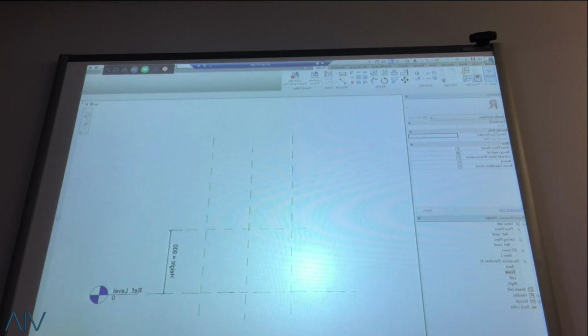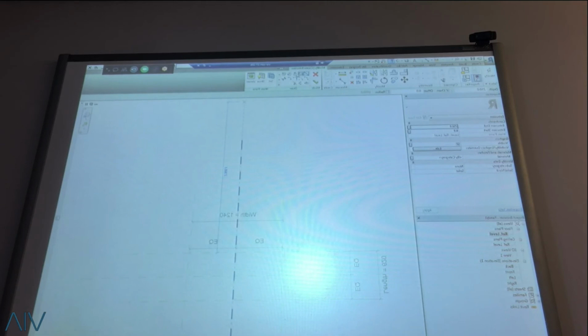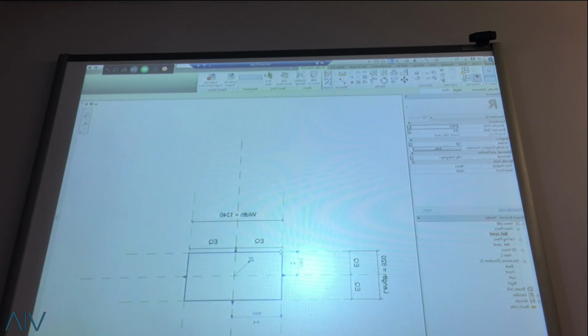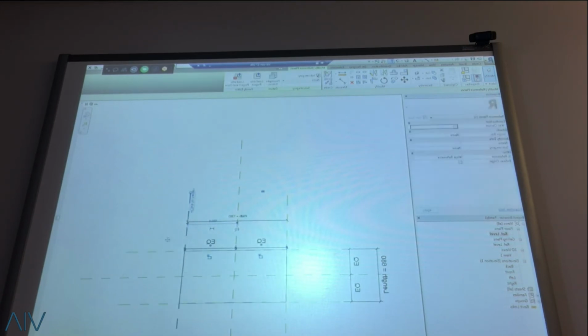But once it gets too complicated, I would just build it out. That's the advanced stuff. I will probably talk about that in the future, like what to do if there are too many reference planes and how you handle that. Right now you have very simple stuff, so here I'm just going to draw a box. You don't have to lock anything. All you have to do is reference those reference planes. When you stretch this out, see that it follows. Once you've built your skeleton, everything just falls into place, and you basically just trace it.